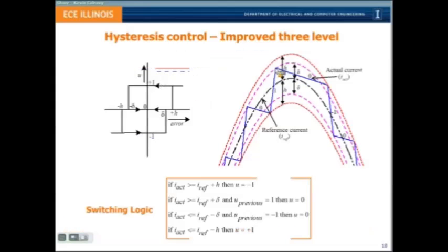So when we do this, the resulting scheme of tracking will be like this. There is a small error that's still there that cannot be avoided, but one can say, okay, let's make this dead zone push up all the way up to here. But there is a drawback which will be seen because of high switching frequency components, which we will not see right now. So all we need to know right now is this frequency reduces the average tracking error, and the switching frequency is reduced because of the use of zero states.